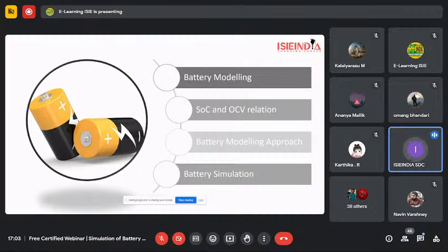After that, at last, we'll do a MATLAB simulation. We'll do some hands-on MATLAB, in which we'll be designing a battery model, including the internal resistance, and looking at the effect of the battery internal resistance during charging and discharging. We'll talk more about that, and also about the different equations used for knowing the SOC of the battery and the terminal voltage.